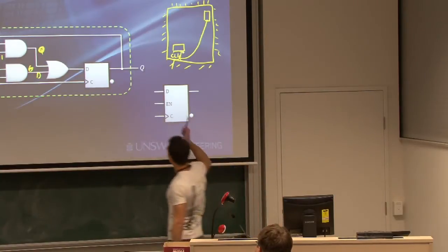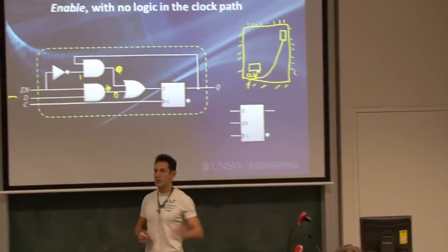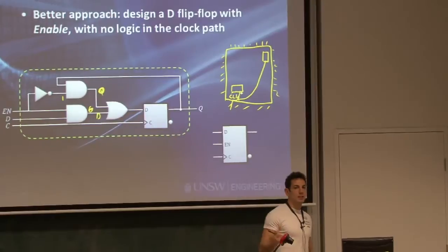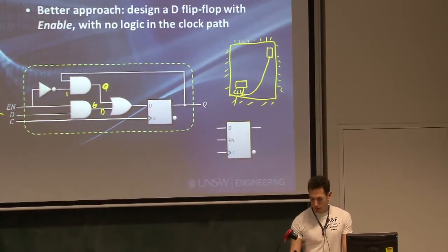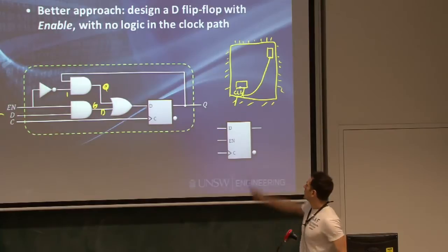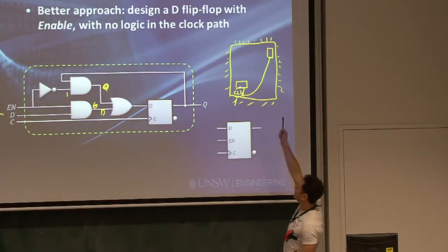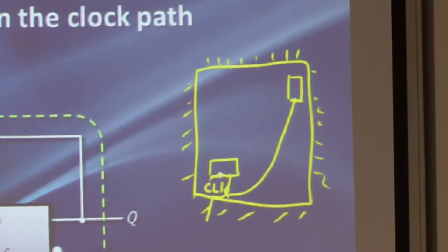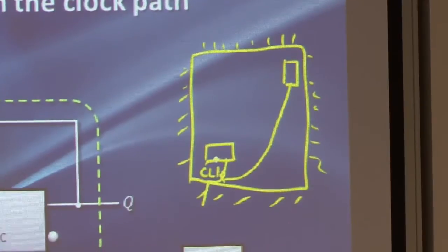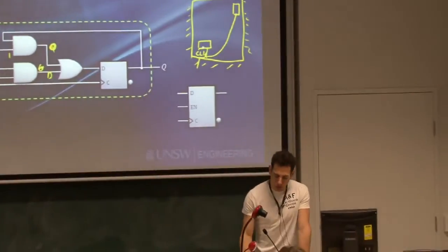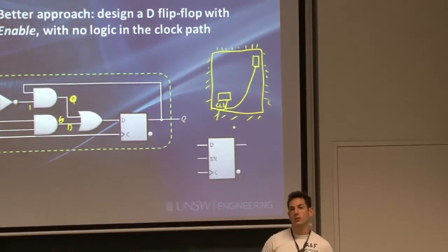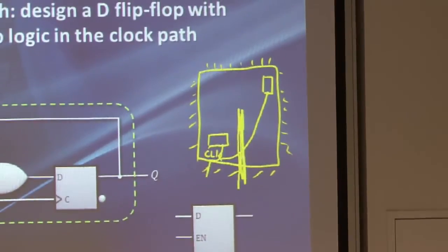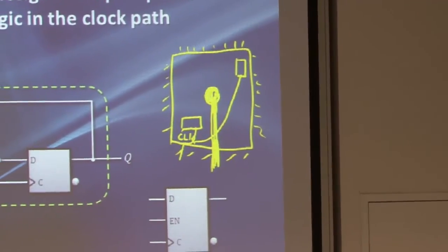However, when we talk about the frequency at which we are clocking our chip and the propagation delays through our logic, these delays do become significant, and this slight difference between the clock signal here and the one at the top is actually going to present us with a problem. What they do these days, and this is true, is take the clock signal through what's called a clock tree, and they bring a really thick wire into the middle of the chip.